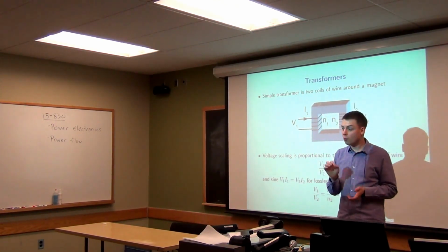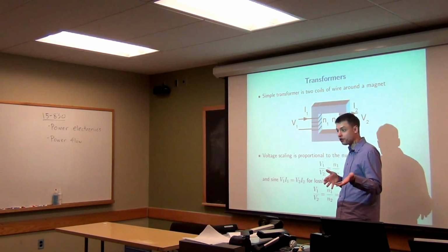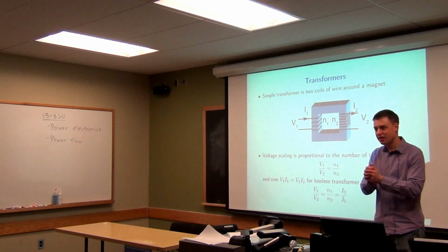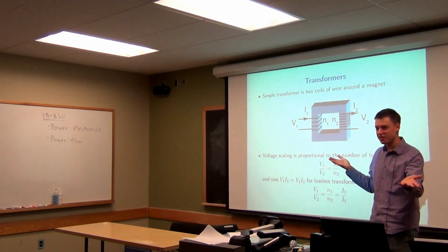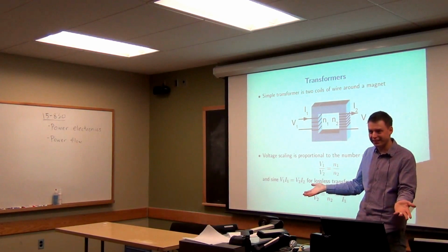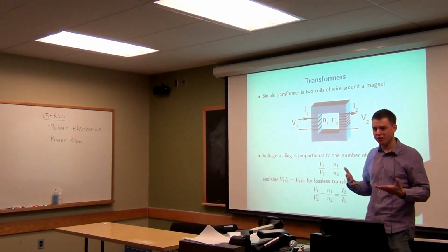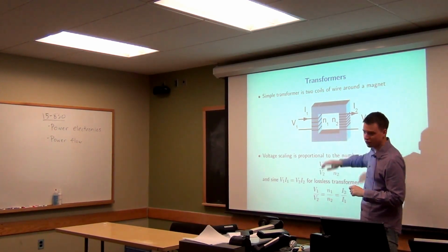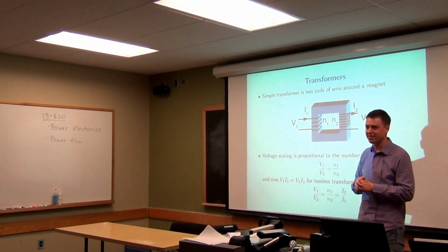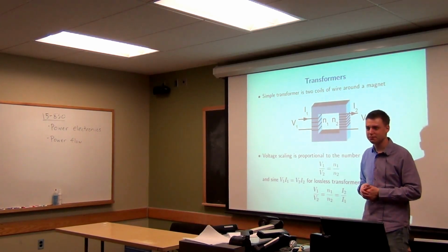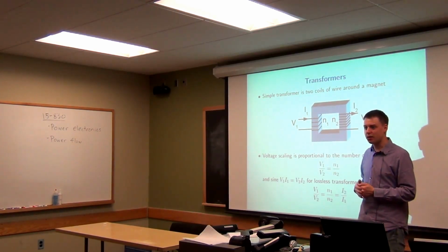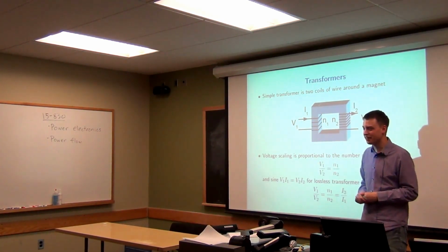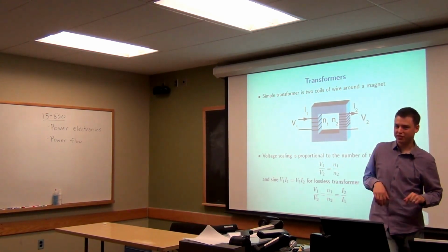This is actually a big issue more and more now, where there are more and more, say, electric cars being used by people, and so all of a sudden they have much more power consumption than the utilities ever thought homes would, especially at night, where they think there's going to be very little consumption. And so oftentimes, if you are on a block where everyone buys an electric car, you have to think about actually upgrading your transformers on that block to prevent things from overheating and blowing up. So it's an interesting issue that comes up as people get these electric cars, which are more efficient and can be more sustainable, et cetera. You have to think about changing the infrastructure to account for these things.